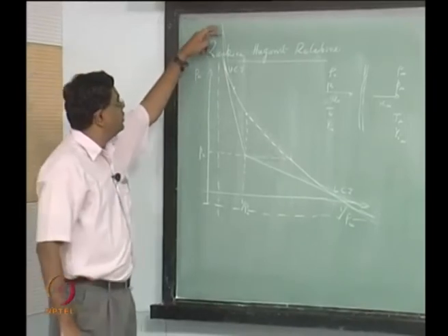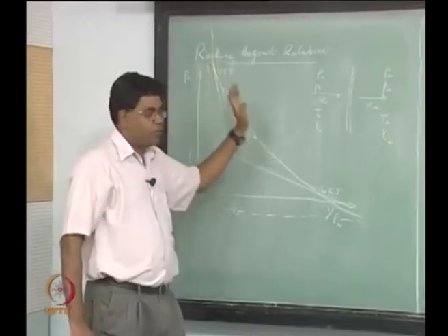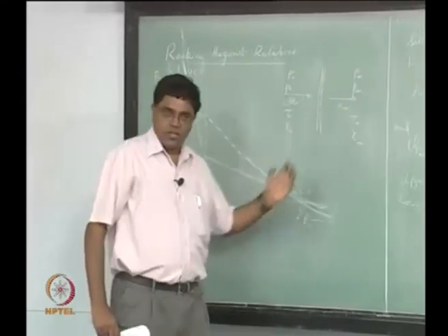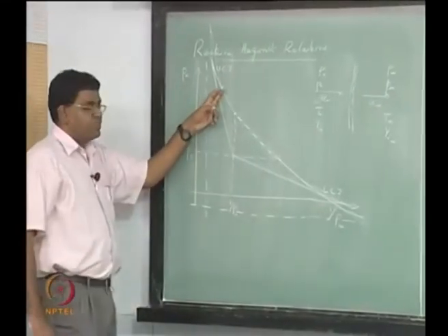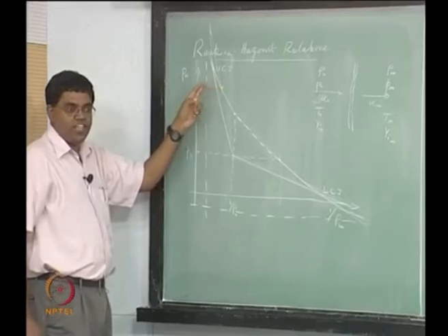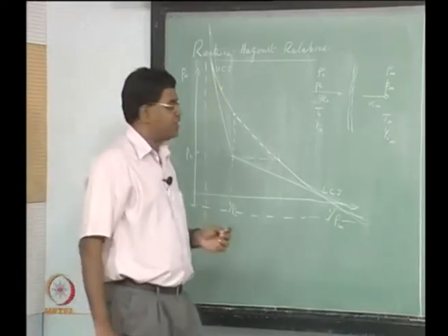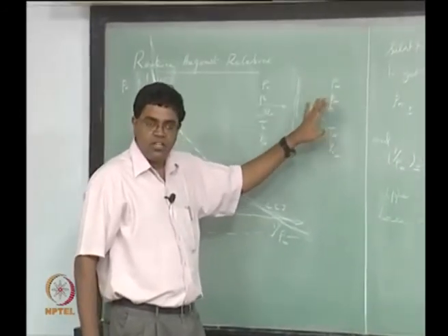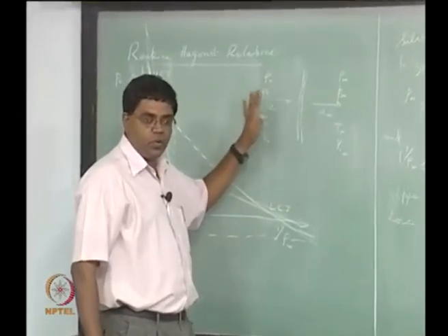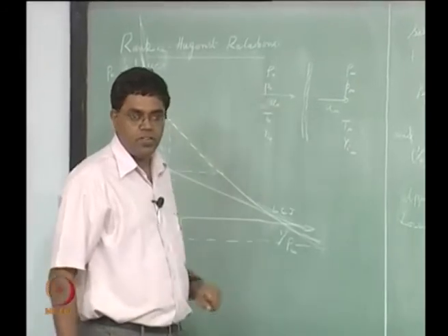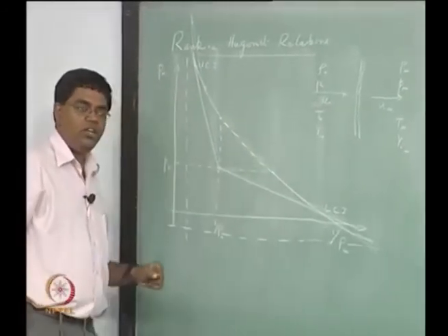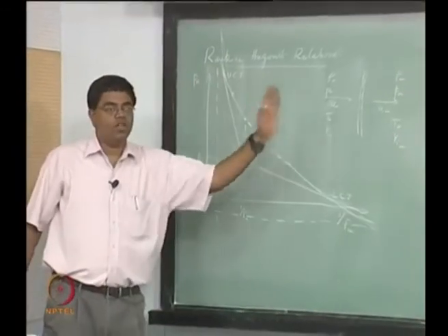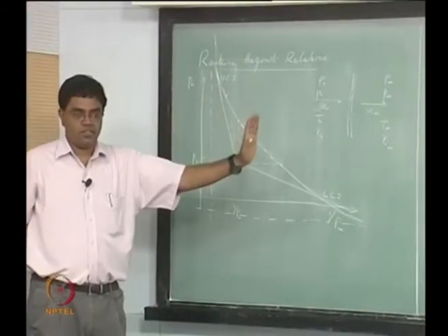Therefore we are expecting it to get a lot compressed and therefore a lot decelerated, so it can get down to subsonic speeds over here, and on this side it's not going to be that much compressed, therefore it's not that much decelerated. So you could expect that this is not decelerated down to subsonic speeds, but it's supersonic, yet slower than the incoming supersonic speed, and therefore we need to anticipate that at the Cj point the outgoing wave is actually going at sonic conditions, right.